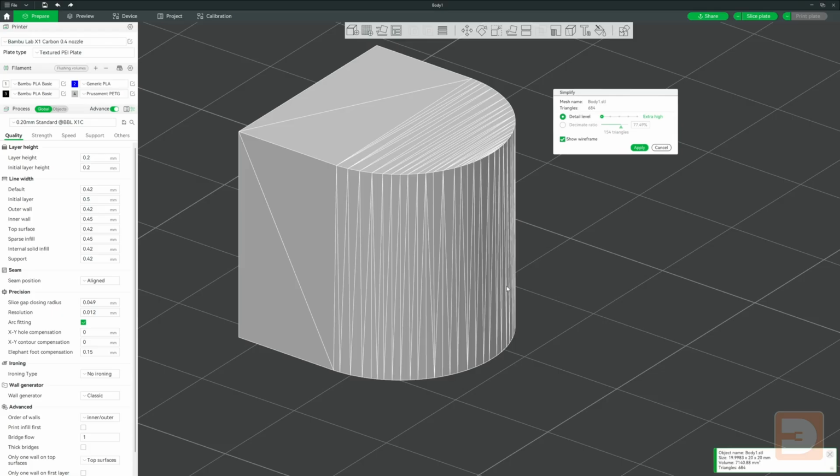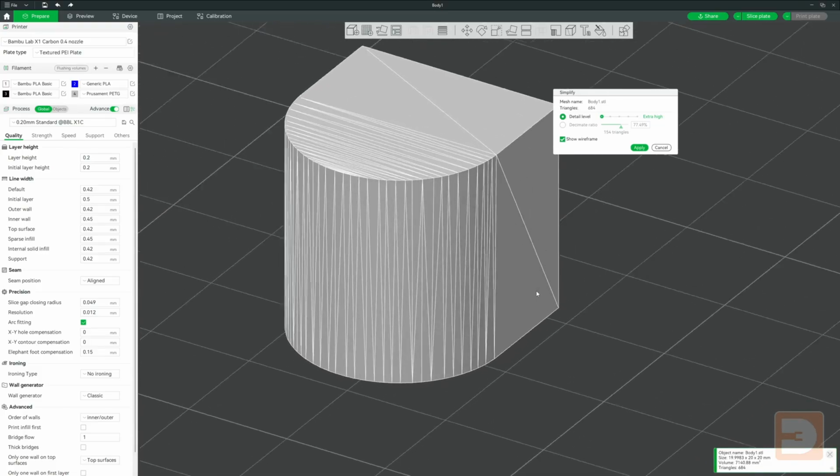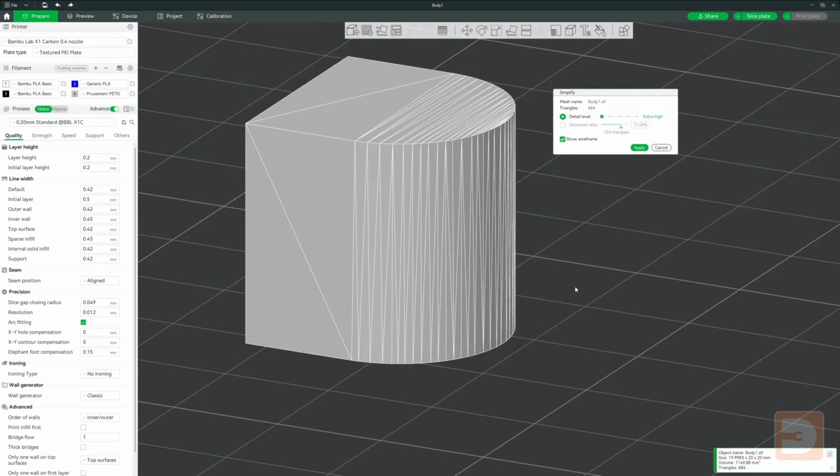Not only does this result in a long list of commands in the G-code file, it can also take longer to actively print, make more noise, and depending on the resolution of your print, can reduce the quality of the curved edges. Having arc fitting enabled tells the slicer to look at the areas where curves are created by flat triangles like this, then it figures out a constant curved line that flows through each of these points.